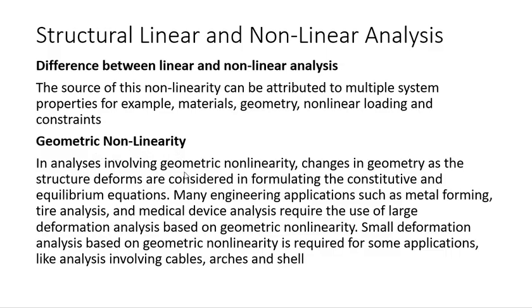In analysis involving the geometric non-linearity, changes in the geometry as the structure deforms are considered in formulating and constituting equilibrium equations. Okay, then many engineering applications such as metal forming, tire analysis and medical device analysis require the use of large deformation analysis based on the geometric non-linearity.